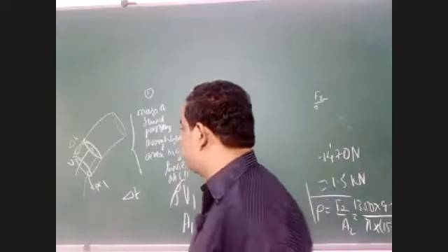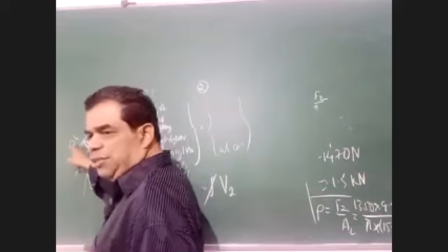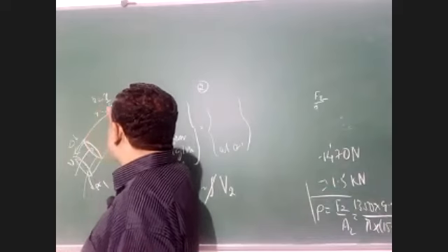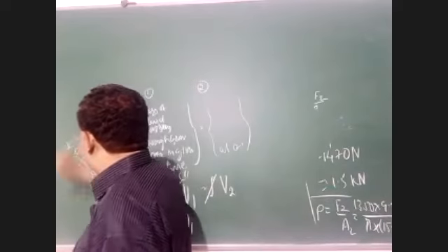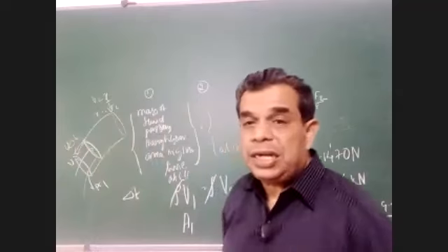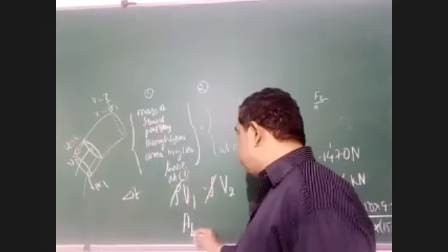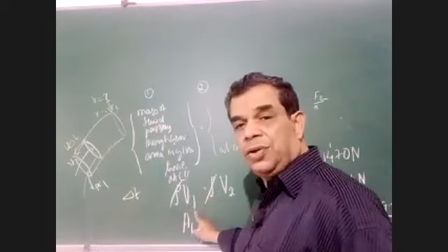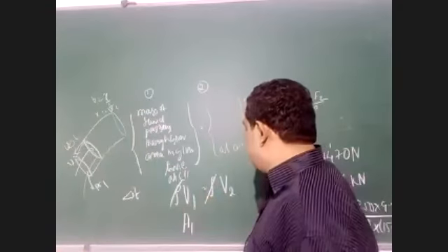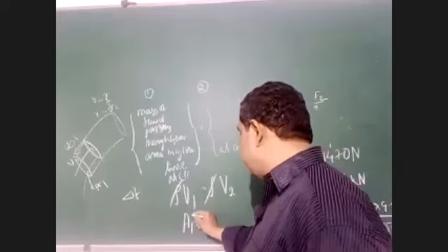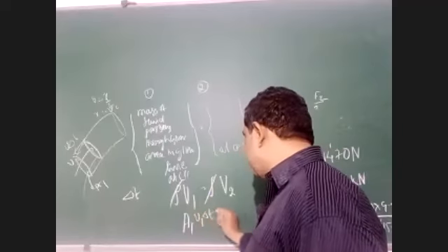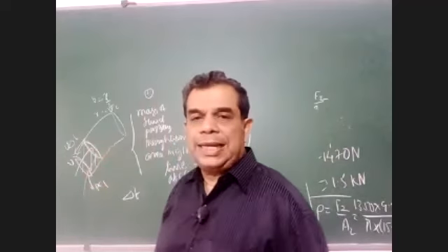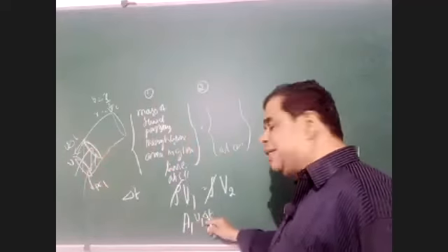Nice. It is right, Surya. It is velocity into time. Velocity is x by t, so distance is x equals v into t. So distance is v delta t. So similarly, the distance at 2 can also be written. We write first for 1. How to write? Rho into V1 delta t volume. Agreed? Area is A1 and this length is V1 delta t. Area into length is volume.